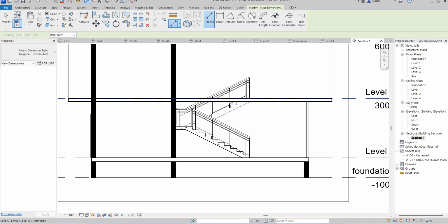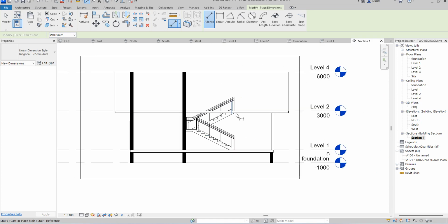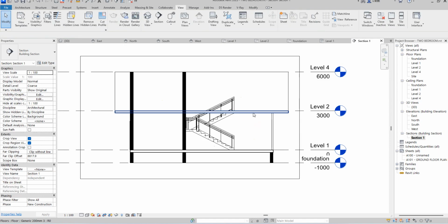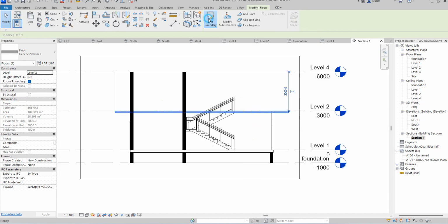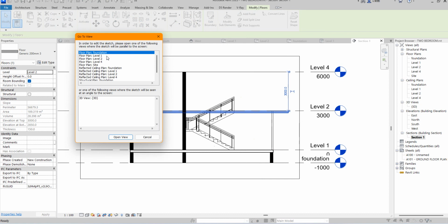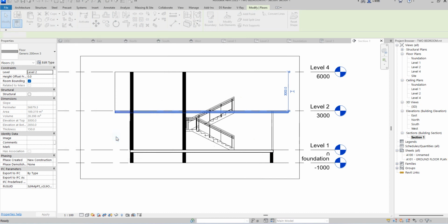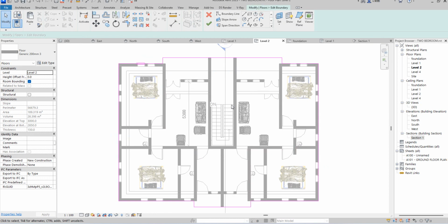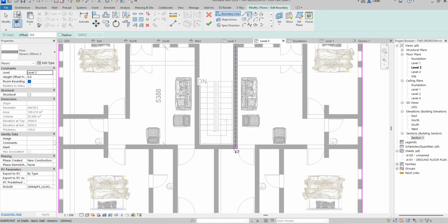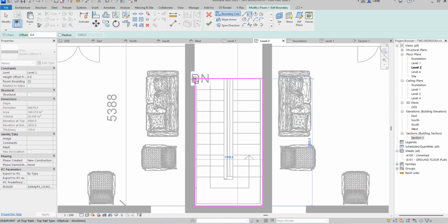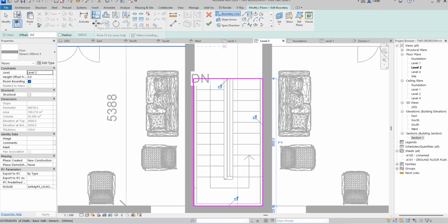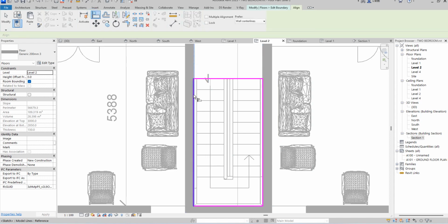When you look at it the way we have done it, this course is called the slab. So we need to edit the slab so that we'll be able to see it from the plan, the whole length of it. So what will you do? I will just click this rectangle, and open only the slab alone. Since it's a perfect rectangular space, I don't need to do more extraordinary things. So I will just adjust that one and click Finish.